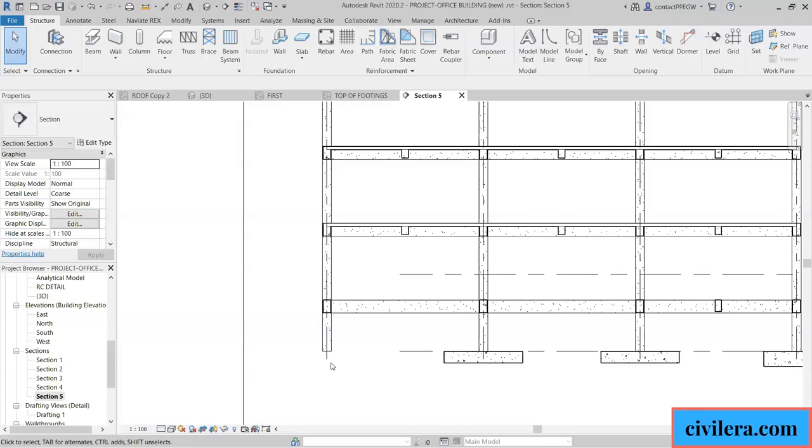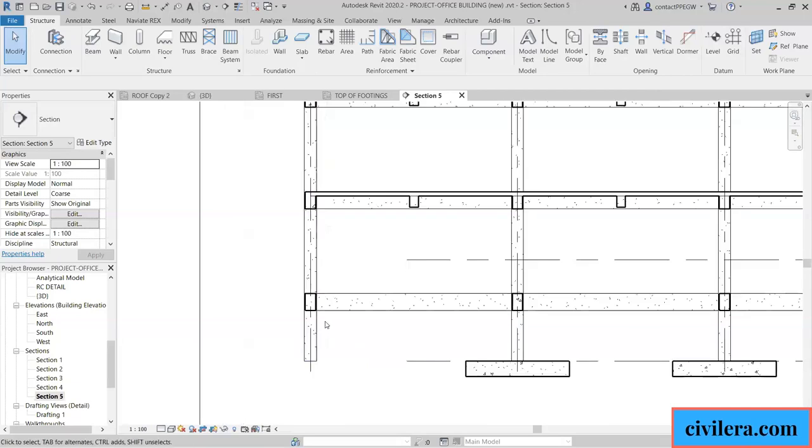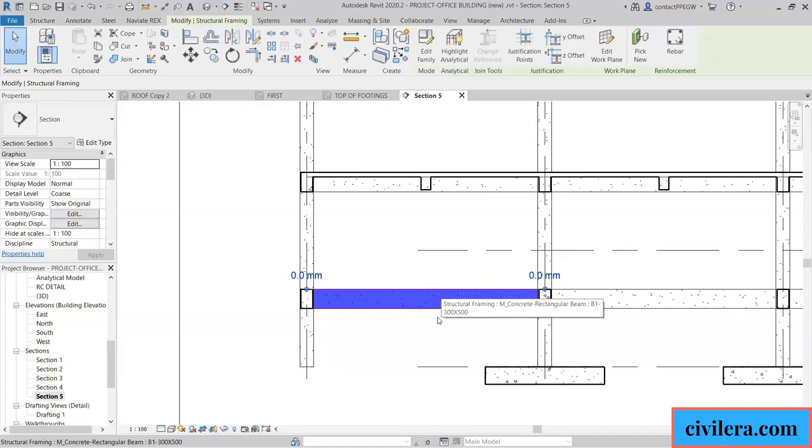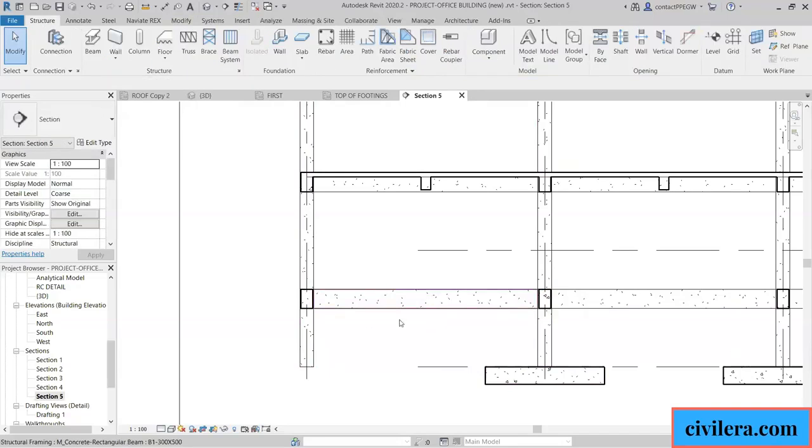It's the same way. So the quantities, if you have taken out, you can even take quantities in Revit. So if you have done all this, automatically all the interconnected things will change. The same way, imagine that you have an RC wall here, say in this location, under this beam, you have an RC wall. The moment you make this beam shallower, say the depth you reduce, the height of the wall increases.